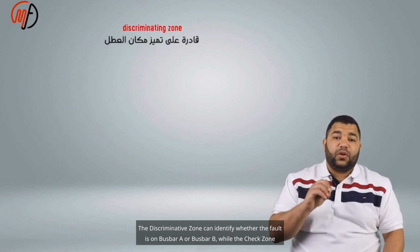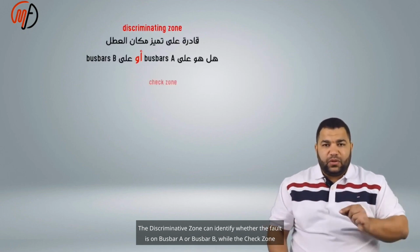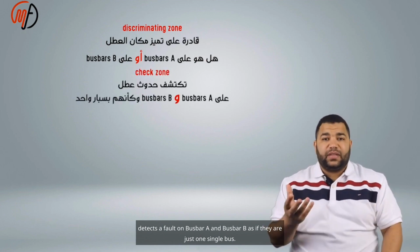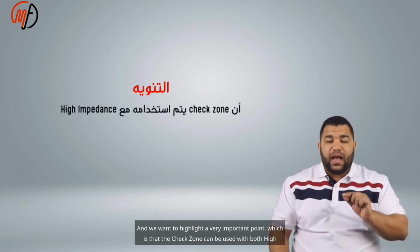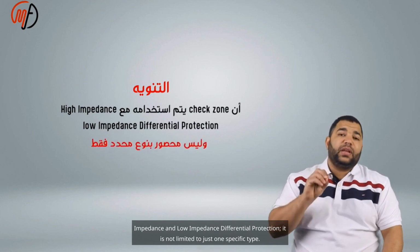The discriminative zone can identify whether the fault is on bus bar A or bus bar B, while the check zone detects a fault on bus bar A and bus bar B as if they are just one single bus. And we want to highlight a very important point, which is that the check zone can be used with both high impedance and low impedance differential protection. It is not limited to just one specific type.